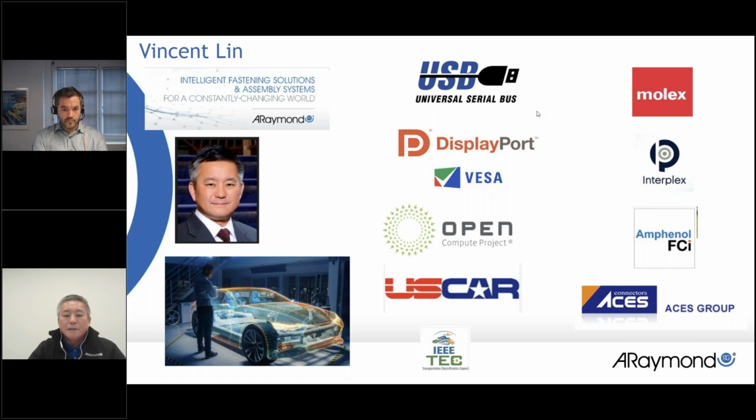I believe for EV adoption, the problem of the EV industry right now is cost, right? Everyone's trying to reduce cost. The high power connector industry is a brand new area. From all of the connector standards I've been very familiar with, and the testing, all of the standards are actually still based on a 30 amp maximum current, 30 amp per circuit in the PCB environment, with a natural convection test requirement.